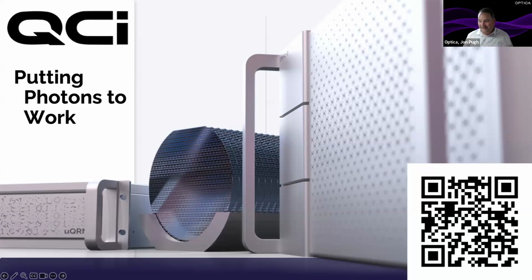Great. And there's a fairly technical question on poling in the future. Do you plan on providing apodized poling in the future? Would that be very difficult? That's not something that we looked into currently, so we don't know at the moment. Great. And you showed PPLN for Z-cut lithium niobate. Do you also have the process established for X-cut lithium niobate? Yeah, we've tried both X and Z cut, and for some technical reasons and yield issues, we're at the moment focusing on Z-cut. But we have done X-cut as well.